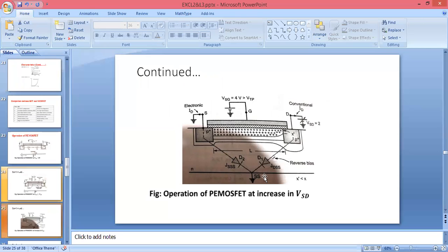हाँ, तो यहाँ पे क्या किया मैंने? I am giving here VGS, it means minus VGS, as well as I am increasing value of source to drain, means minus VDS. At that time what will happen? This biasing, reverse biasing will happen heavily. That's why we will get here constant value of current.